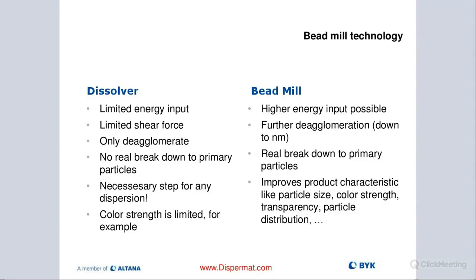In the milling process, obviously we use speeds, we have a rotor, a lot more elements in play, allowing us to put in much more energy into a mill base, really now reducing the aggregates down to primary particle size. That will give us the best looking product, and also helping us save the most amount of money because we're increasing the surface area dramatically when we are milling.